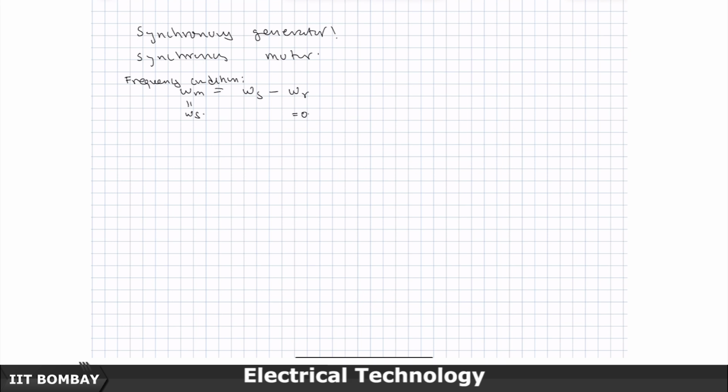Now, I connect a load, maybe a 5 ohm load at unity power factor or whatever. The moment I connect the load, the rate of change of flux, which has created induced EMF, will circulate a current through the resistance, which is E by R if it is just a pure resistive load, and this current is created in such a way as to oppose the change.